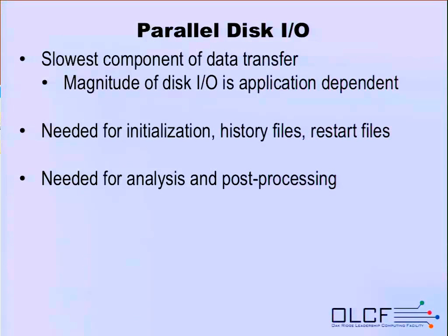You need data to initialize your model. You need to write history files out to analyze later, or why else are you using a supercomputer. You need restart files in case part of your nodes go down. The technology for restarting is not the greatest at this point. There's a lot of research going on, but it hasn't made its way all the way to the front yet. But you need to restart the simulation. So this is needed for analysis and post-proc.